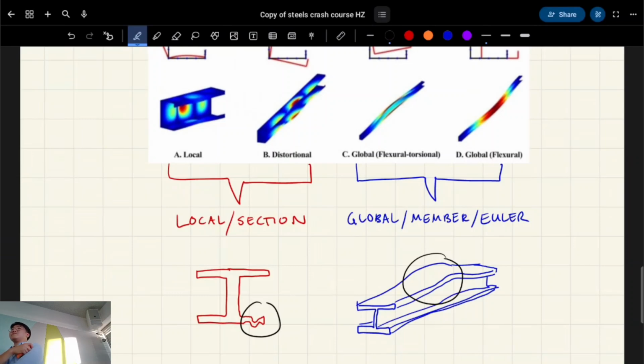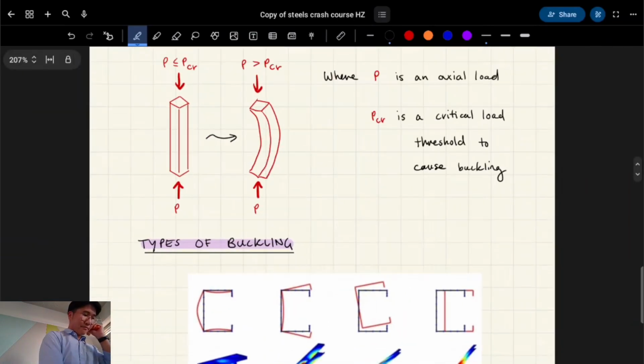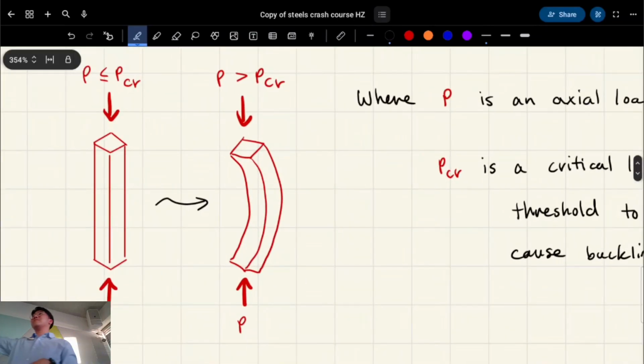And then the local one is just like in that example, it's only applied in the cross section, within the cross section, right? So there's a different axis we're looking at, right? So in concrete, say you have a concrete column. Pretend that's a concrete column. Generally, they're shapes like this, you know, rectangles and things like that. They're not really susceptible to local buckling.